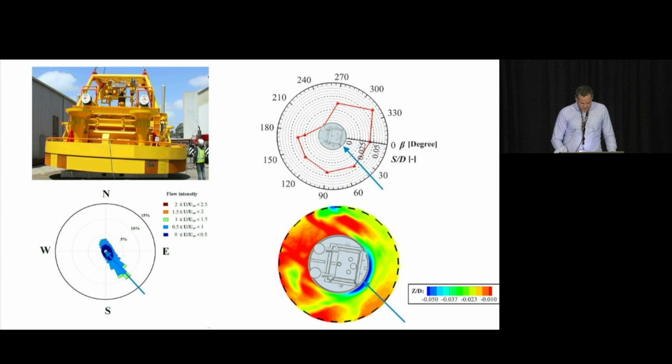And as a result of that, this is a scan profile from the model scale experiment, where you can see the scour pattern here. Obviously, blue colours are scour depressions, red colours are sort of, if you like, deposition locations. And if we run around the perimeter of this model structure and we plot it on top of the observations, you can see that we match a number of aspects of the scour profile we see in the field. We definitely match some of the asymmetry we can see in the field. We match the extent of the scour.